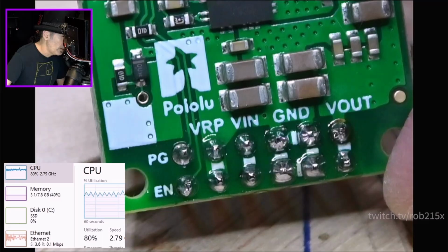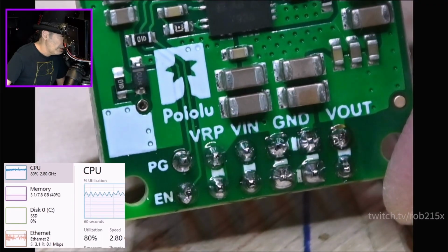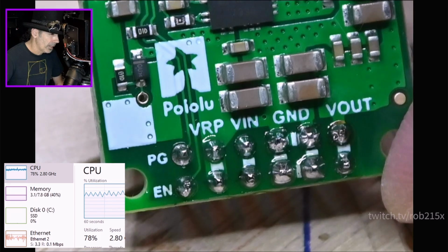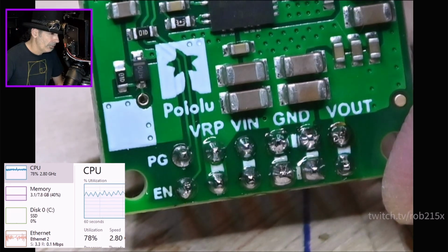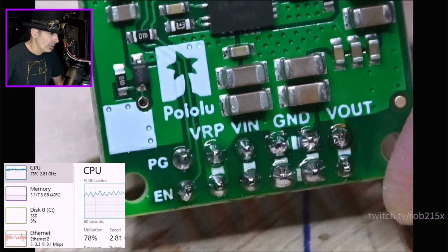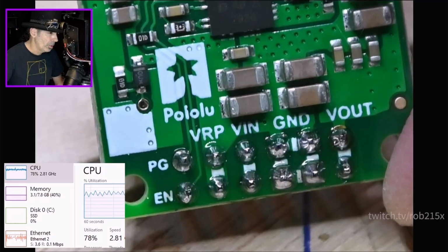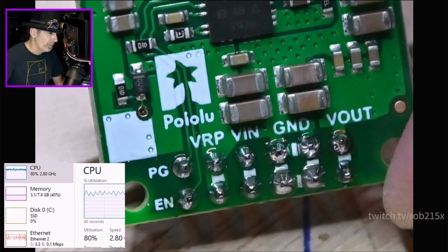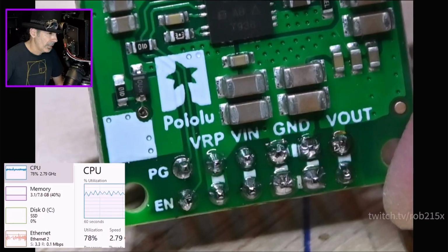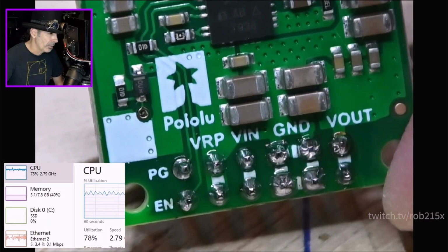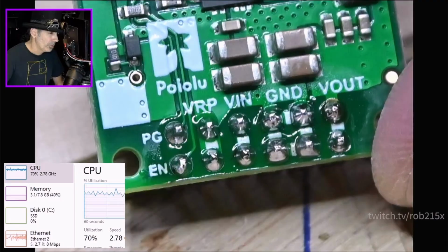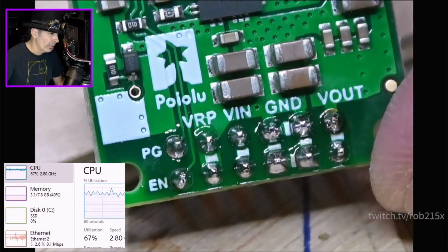Now we're going to use both wires, so we don't have any kind of problem with amperage or overheating or anything like that. The next 4 pins from the right are ground pins. 2 of those are going to be for our output, and 2 of them are for our input. All ground wires are connected together. And then the V in is going to be our 24 volts in from our drone battery.